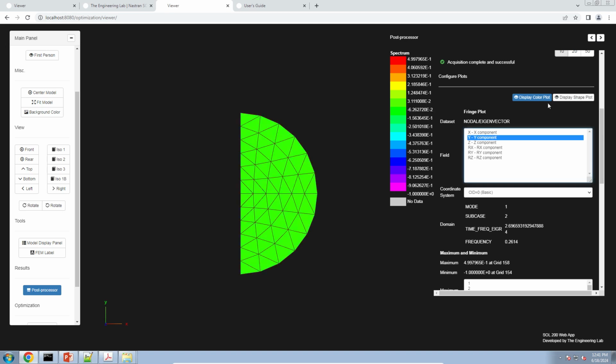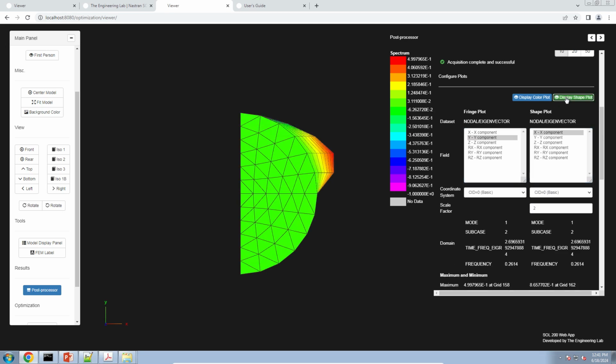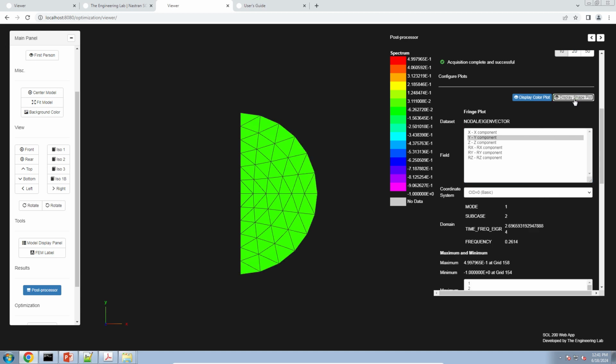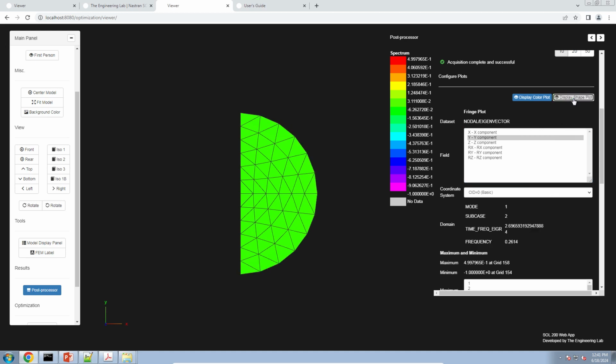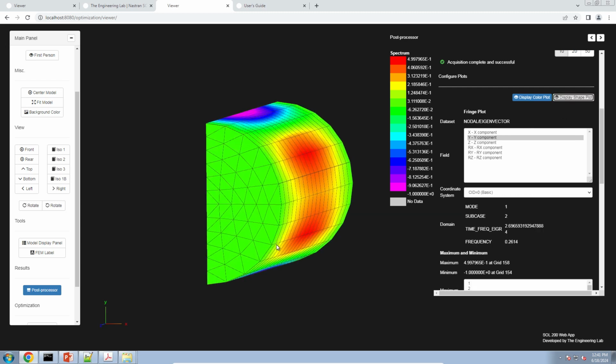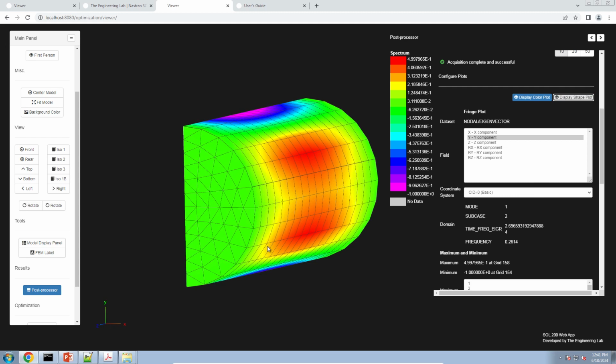What about the y component? What does that look like? I believe this would be a vertical change in the eigenvector. Here you can see that the nodes are moving vertically. But we want to look at these results from the degrees of freedom, or the displacement coordinate system.